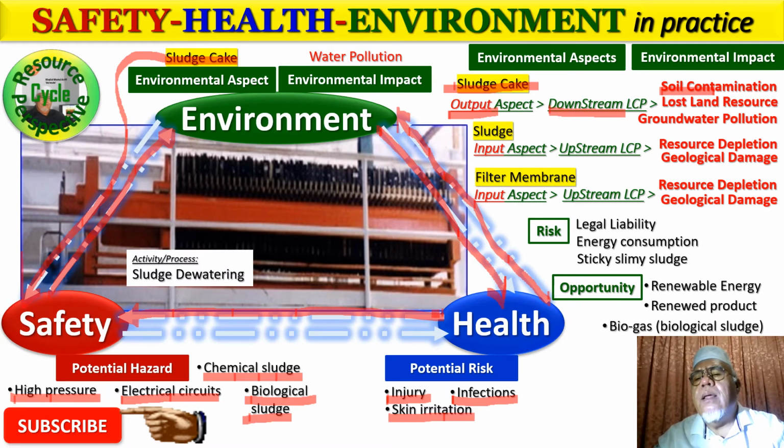And over there, the sludge cake would interact with the environment, would degrade itself, and therefore form some leachate that would eventually leach out from the secure landfill. A secure landfill is not 100% secure because the earth moves and there's vibration all over, and eventually it will crack, and this leachate would eventually contaminate the soil underneath the secure landfill base.